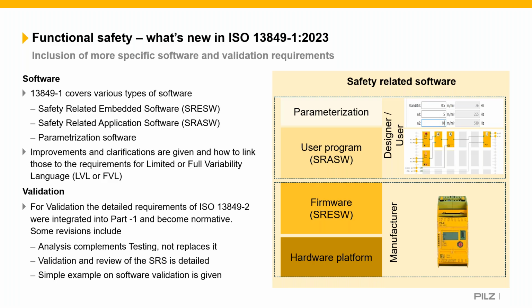Full variability software is really for computer programmers, where you can do whatever you want within the software. Generally, within safety systems, you'll be looking at more of a low variability software, that'd be the multi or something, or even pre-configured function blocks and things that will be in your more complex safety PLCs.